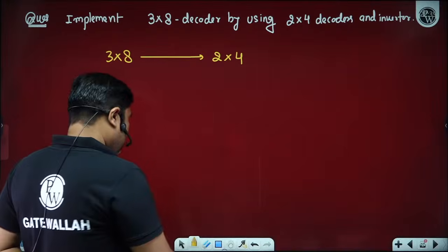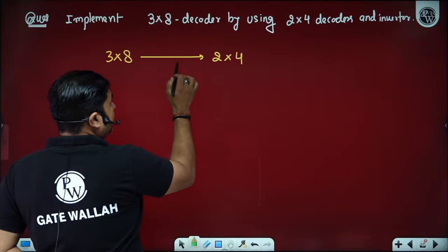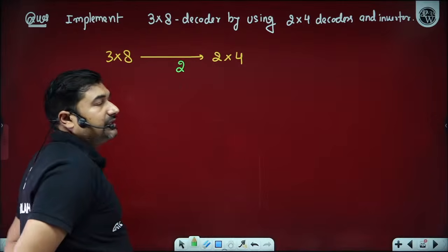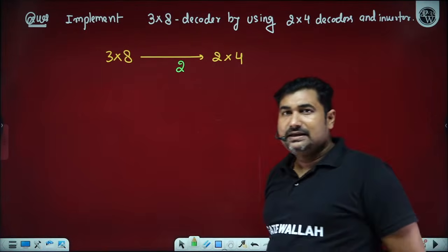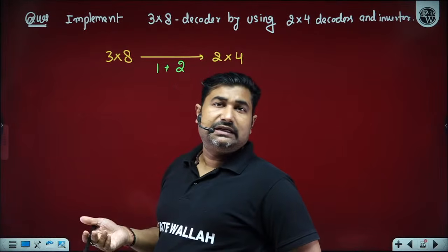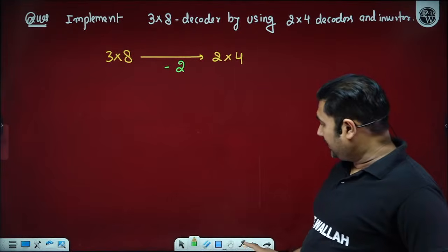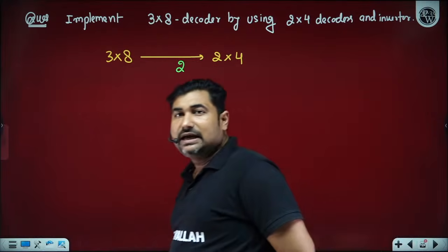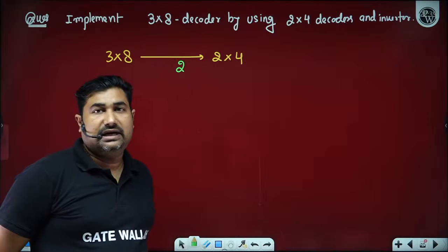Yes sir. So we can divide this 8 by the 4. 8 divided by 4, so 2 times. This 2 can't be divided by this 4. Is it okay? Yes sir. So if you want to design, then what happened? Unnecessarily you are increasing the delay in the circuit. Better not to divide if it is not further divisible. Is it okay? Now we can utilize the inverter to have our desired decoder.